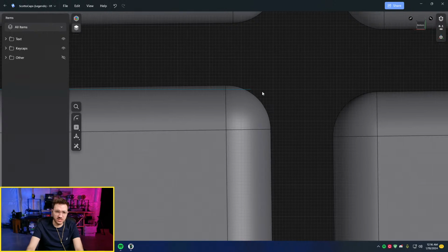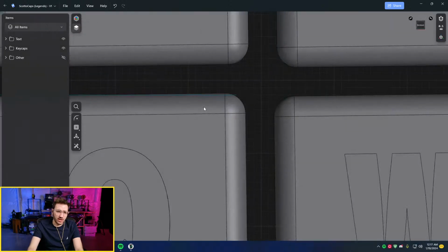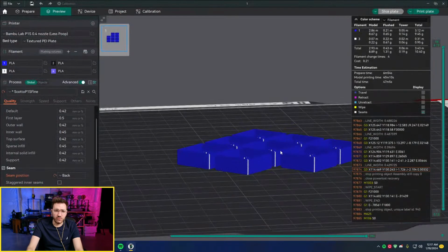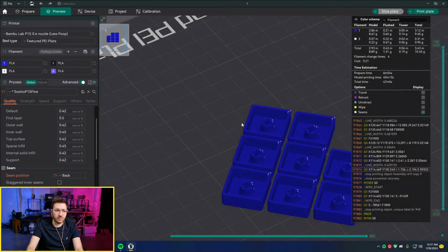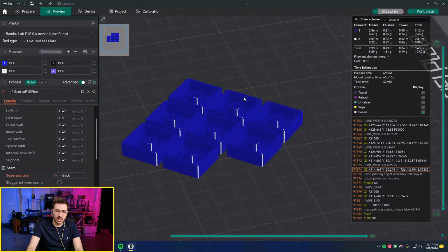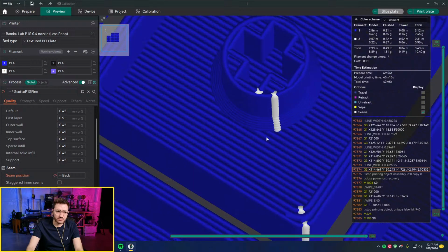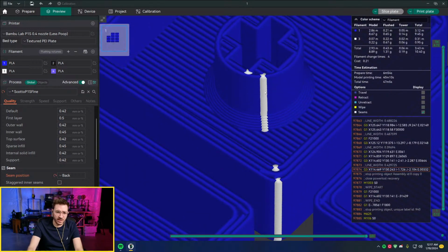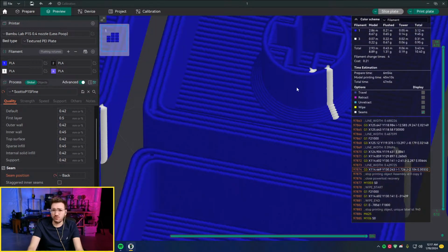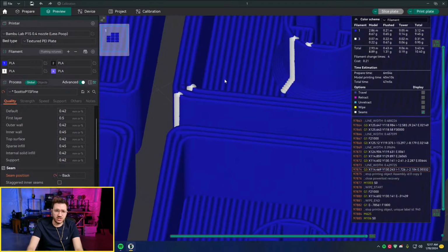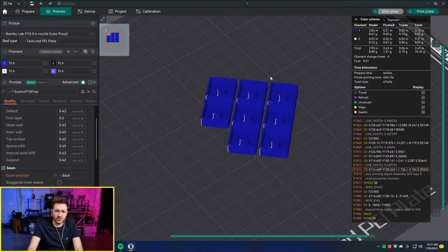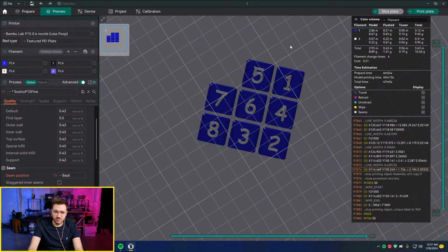And that's just because something with FDM printing results in these keycaps being skewed, so they'll be rotated either clockwise or counterclockwise. So I counteract that by rotating them, and then rotating them again in the software helps a little bit more to align them better. So I do that in 2 spots. And then also by doing the 45 degree, the inner seam gets on the stem there instead of on one of these parts. So it helps with interference issues, so you don't have interference with the switches. It just makes them print a little bit more accurate, I guess. But yeah, those are them.